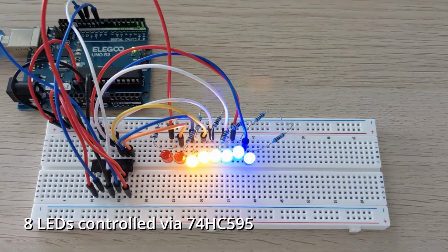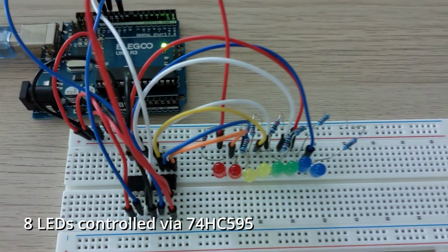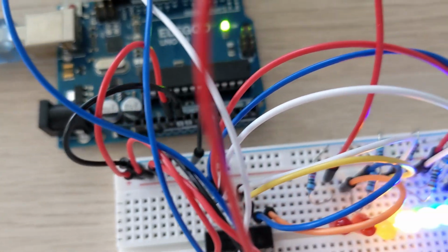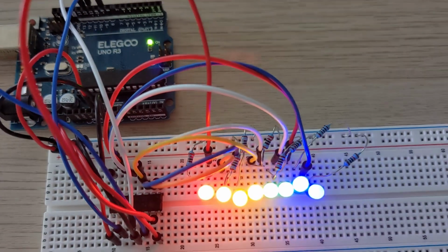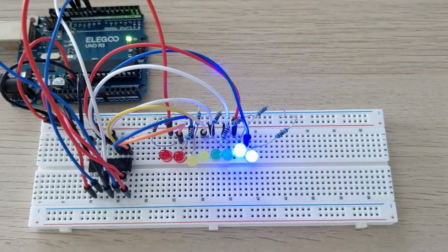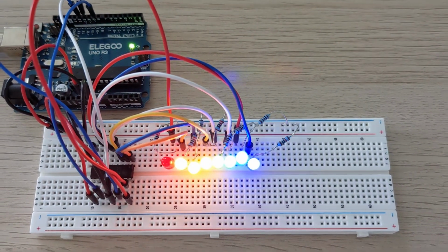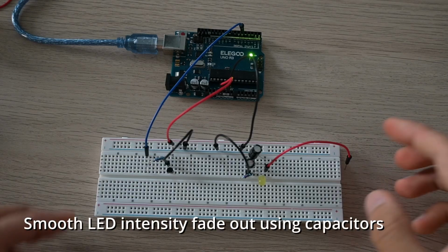Now, since there is a limited amount of outputs from an Arduino, we can attach an IC to extend the number of possible outputs at the cost of some latency. And this IC is essentially a very limited piece of external memory. You write into its buffer the outputs that you want to have, and then use a latch to make them all available in one go, just like double buffering in a video.